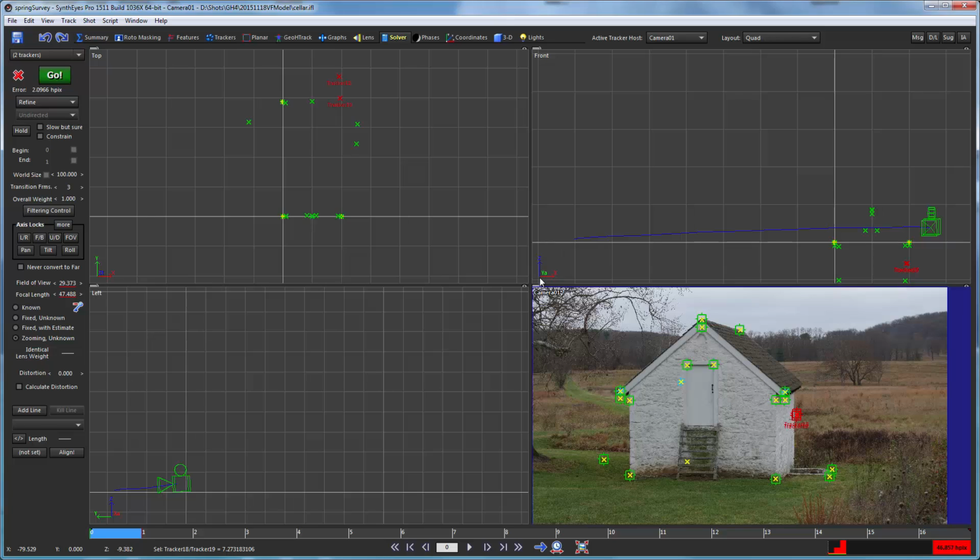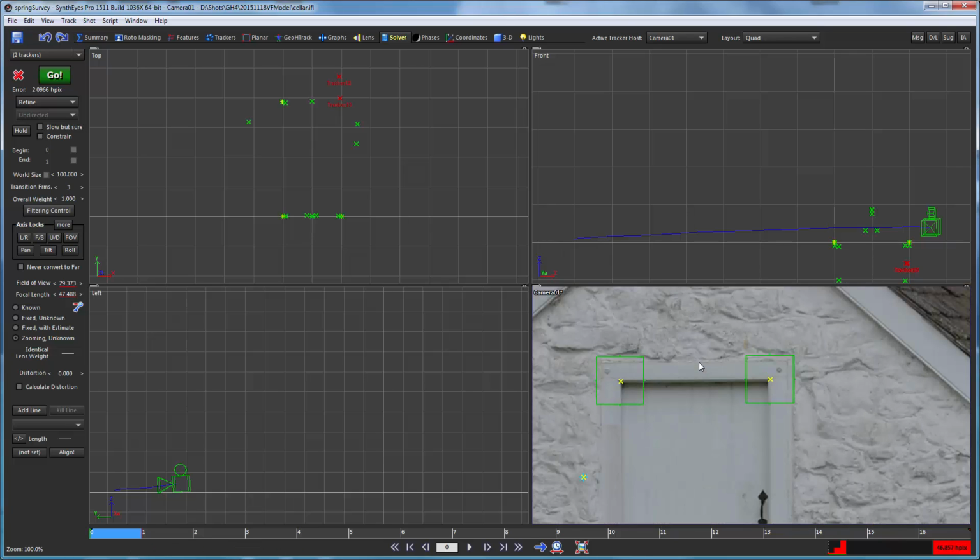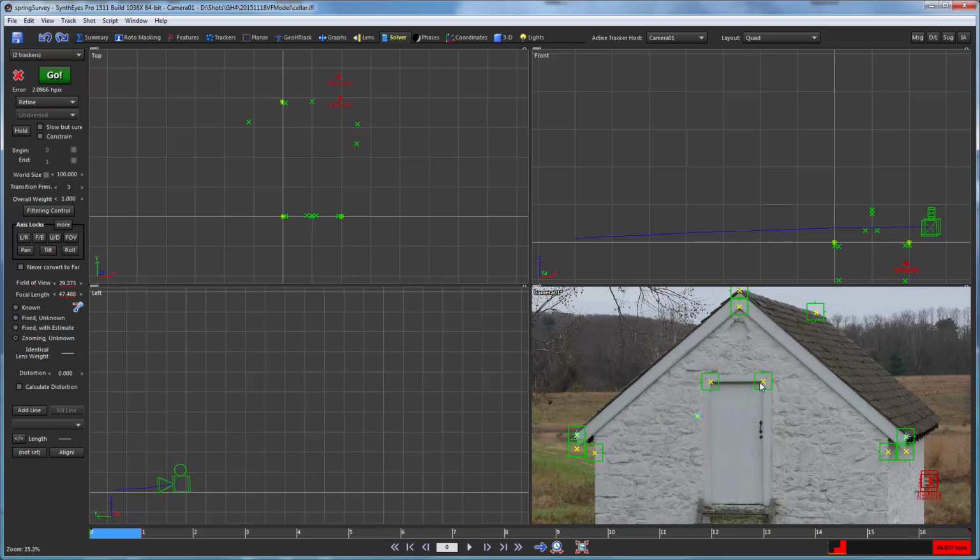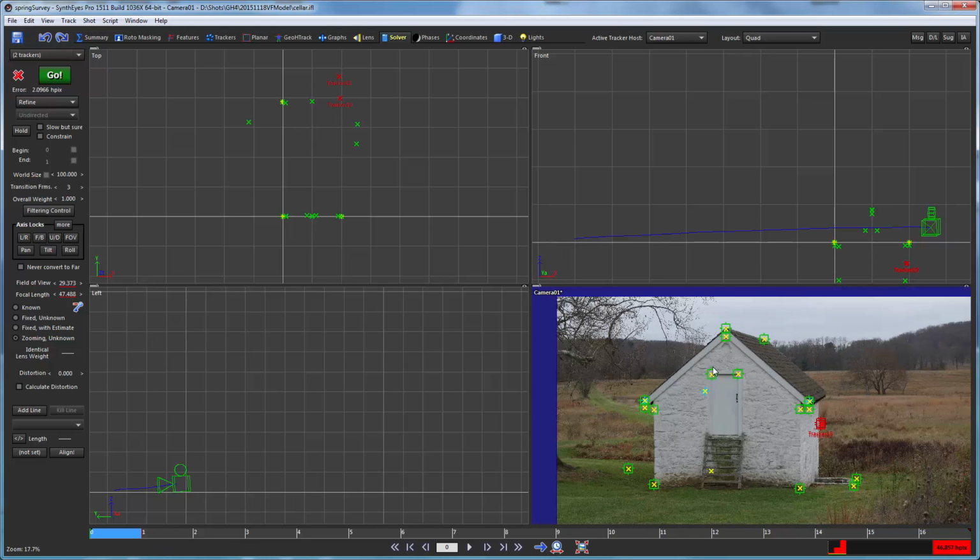So one detail that it would be nice to get right is the size of the building in some tractable units. And, from what I did earlier, you might think, oh, well, we've got maybe a measurement for this door. Let's use this width of the door to set the measurement of the whole thing. Well, what I'm going to tell you is that that is not the best idea. You always want to use as large of a distance as possible in the scene.